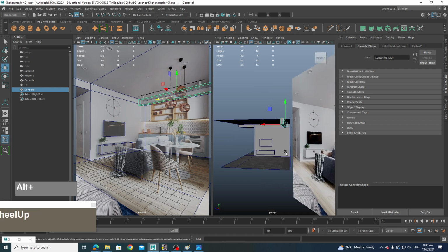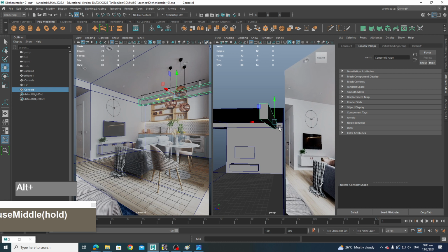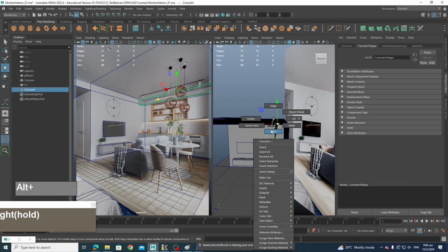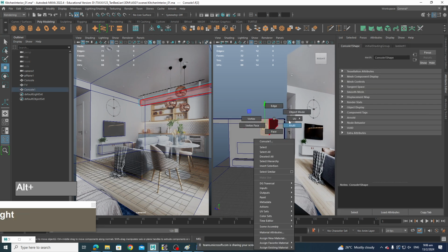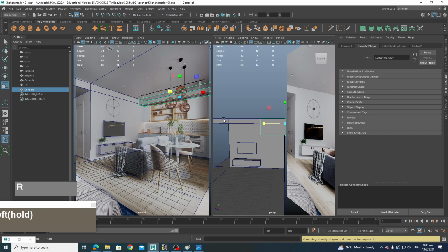Okay, so now if you look over here, we can see that there's a protrusion, there's a space here so that we can build our shelving and also the backsplash for the kitchen cabinet area. All right, so I'm going to duplicate another piece. Actually, now that I think of it, I want to select this entire piece here, push it back all the way until it touches the wall, then using my scale tool, scale it up until it lines up with the protrusion on the reference here. Yeah, this makes better sense.